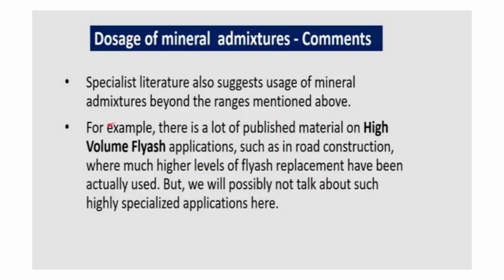And also I feel this is possible because the safety factor is not that much of an issue. Even if the pavement fails in road construction, nothing serious is going to happen. But that is not the case in building construction. If something happens there will be a lot of casualties. So risk factor is one of the main factors associated with its use, because ultimately we want strength.